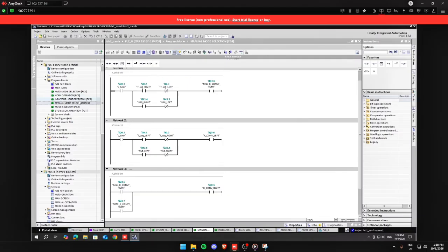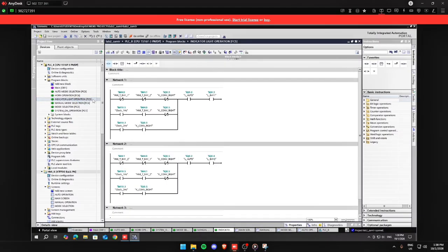Next, the indicator light operation. This function manages visual status signaling through the use of indicator lights and frequency clocks. The B1 and B2 lights, Q0.3 and Q0.4, provide real-time feedback on occupancy and system readiness. The logic utilizes a 1 Hz clock to indicate a ready state and a 2 Hz clock to provide a fast flashing warning whenever the conveyor hardware, Q0.5, is actively in motion.